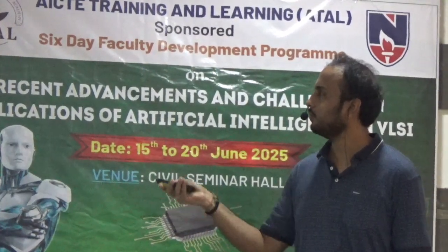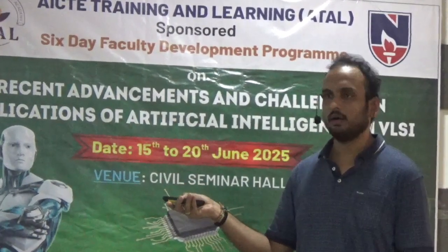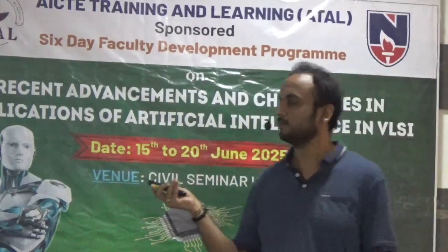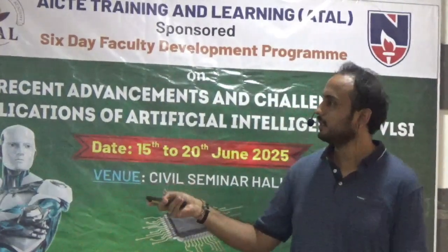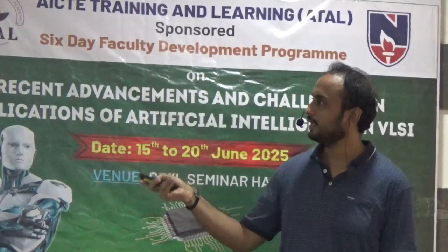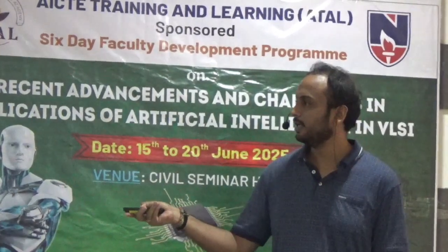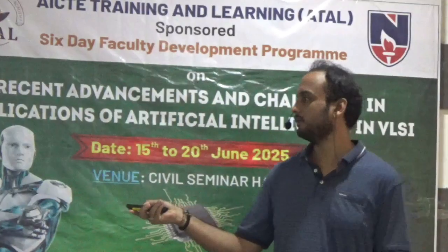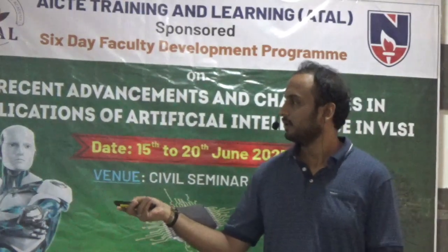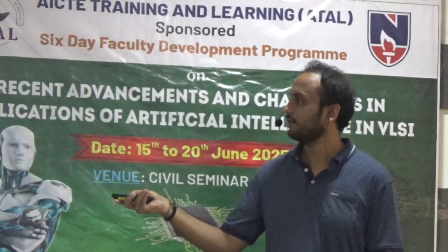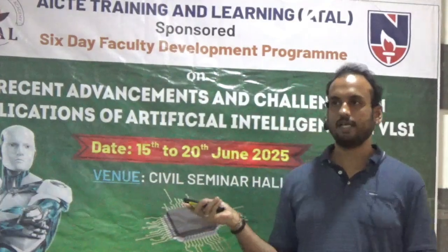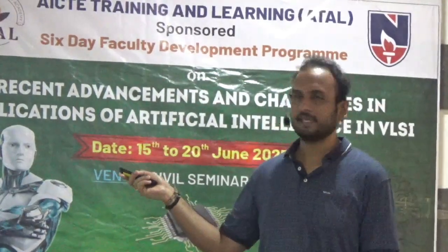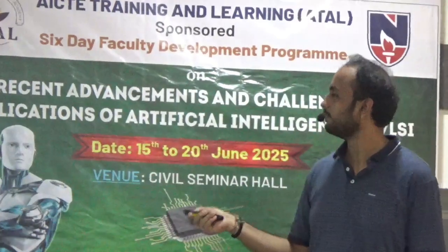And this is how, when you scale down the technology, there are some second order effects like channel length modulation and velocity saturation, so it starts increasing. In the early days, when we are working with 1 micrometer technology, there are very minimal second order effects. When we go to lower technologies like 10 nanometer or 20 nanometer, there are a lot of second order effects we will face.